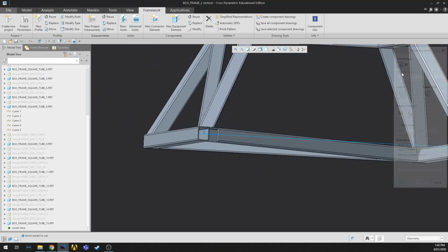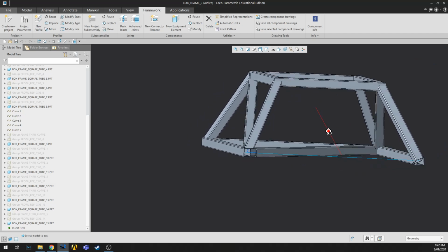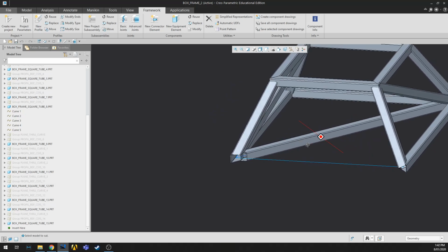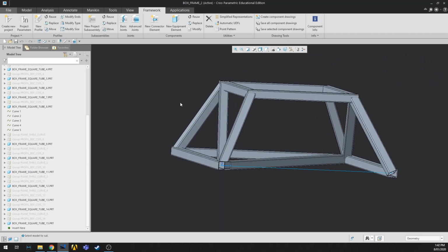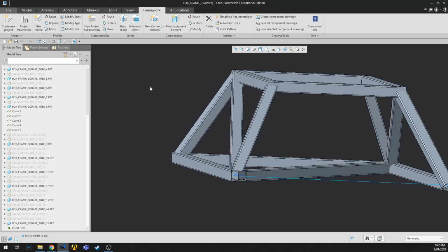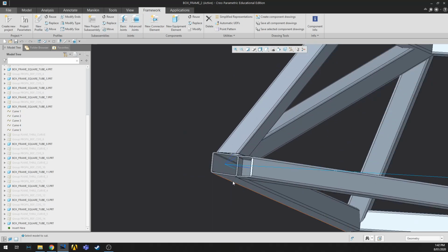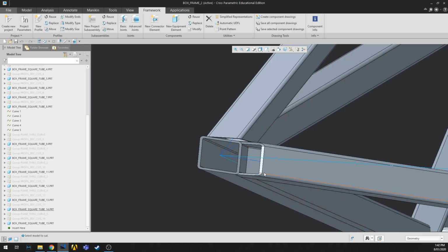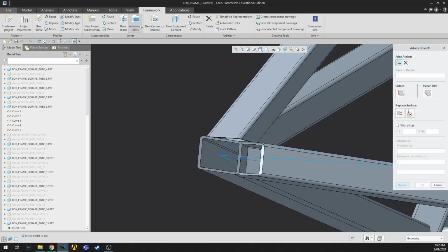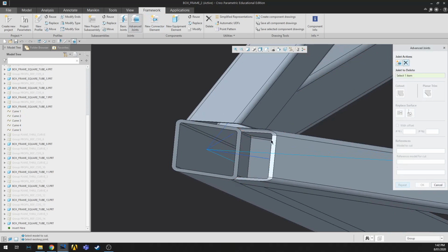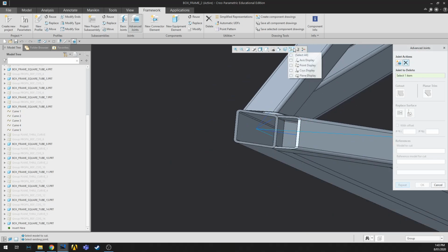Alright, well that's just a basic tutorial on putting frame members in and creating joints. I guess while we're still on joints, I should finish up. If you want to delete a notch, you shouldn't delete the member. You should open up the joint tool, and then there's the delete option here to use. So the advanced joint tool deletes advanced joints. It's a little bit confusing like that.